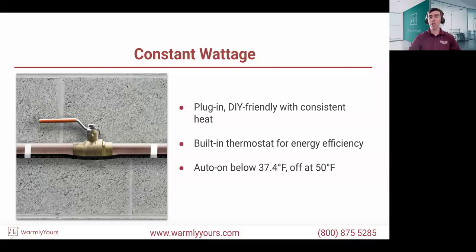One thing I want to quickly point out, we're going to have that in visuals in a few moments. We're trying to use visuals that show you the pipe, the installation, how you tape the cable to the pipe, but we don't show the insulation that always needs to be used when you're finishing everything up. We're not showing it because you're not going to see the cable there, but the insulation should always be used, because that's how you use this heat properly. You have the cable, you correctly attach the insulation, you secure it, and that's how the heat is trapped and stays there.